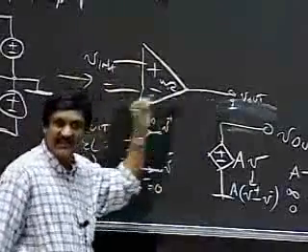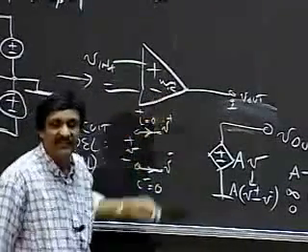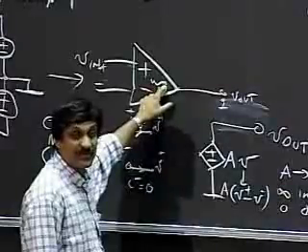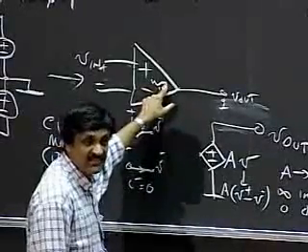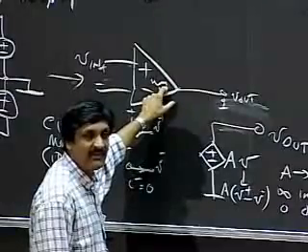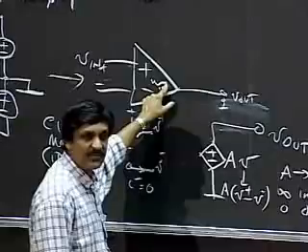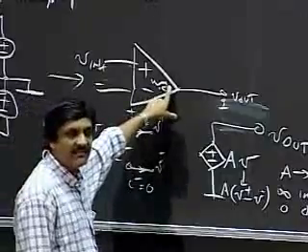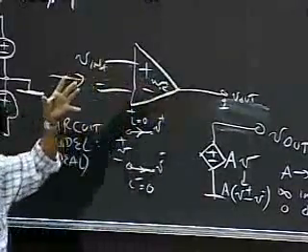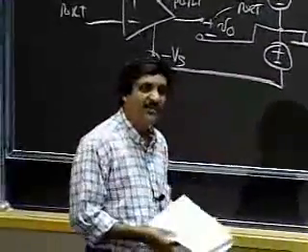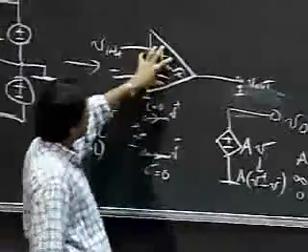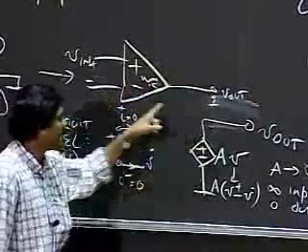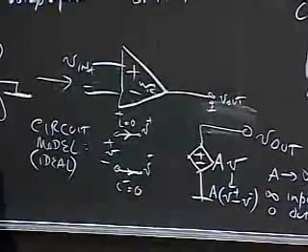It's got a bunch of other circuitry like level shifters and so on. And at the output, it's got a buffer, something reminiscent of the source follower circuit that you learned about in recitations, a solved example in the course notes, and in your homework as well. You saw a variant of the source follower on your quiz too, in problem 2. Remember, for the source follower, the resistance looking in from the output was very, very small. So you have seen some of the pieces that go inside the amplifier, but we will deal with this as a building block and simply represent it using this little abstract circuit.